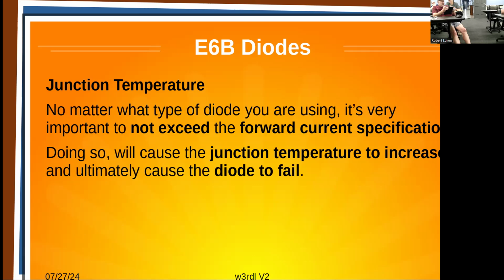When you have a device like that in the circuit, you can have what's called thermal runaway, where as the current's increasing, the resistance is decreasing. What's that cause? More current, more heat. And then you have one of these devices where the smoke got left out.